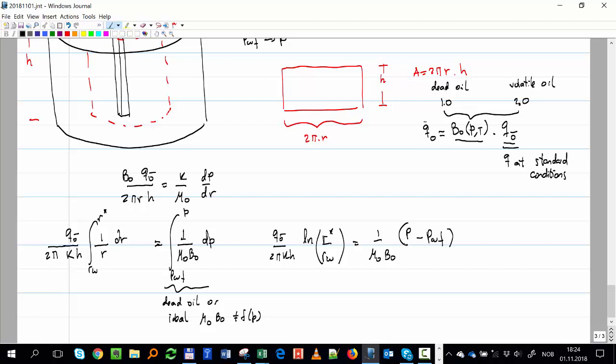Very important. We are now very close. You see, IPR, I told you we have a difference in pressure, okay, and we have the rate, and we have a constant. We are very close to getting our IPR equation that we need. So to use this equation, and you're going to use it now in this next exercise, I'm going to clear pressure as a function of radius. I want to plot the pressure as I move outside of the wellbore, how the pressure will change.